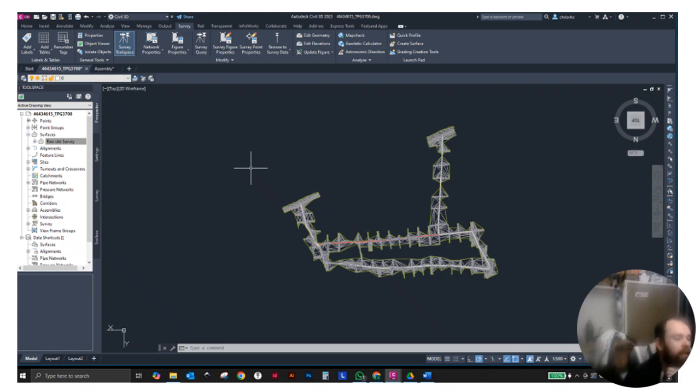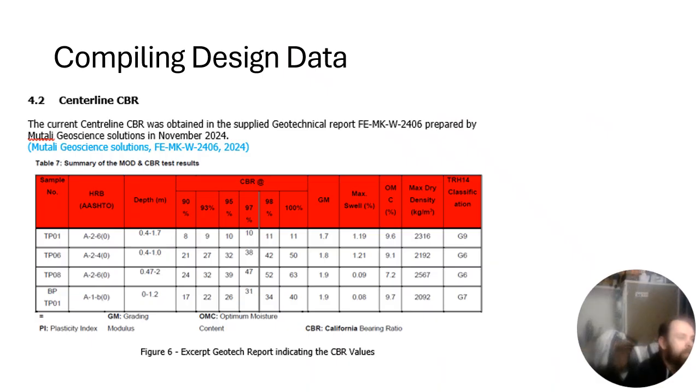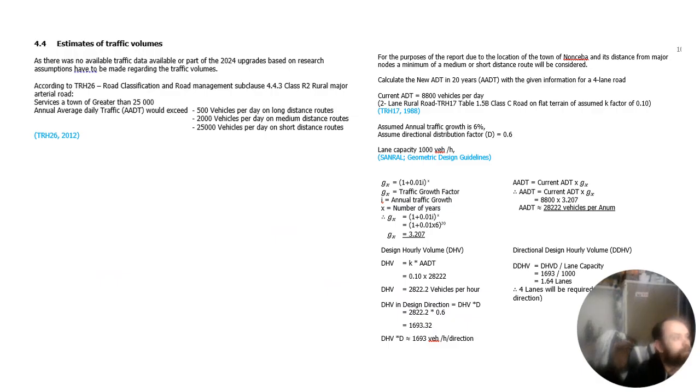Later on when I did the corridor, I had to include a little bit more layer, surface line to call it. Then the design CBR, they did do some, however, they only did it in 3 areas, and this wasn't enough for what I needed. So I eventually, and later on I'll speak more about it, I eventually did some DC correlations for DCPs. I did some estimations of traffic volumes for the expected implementation in about 20 years' time, I said.